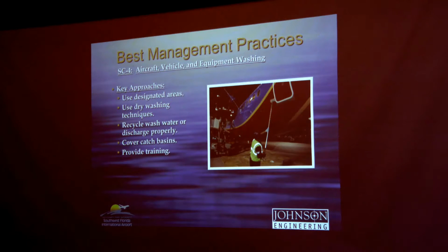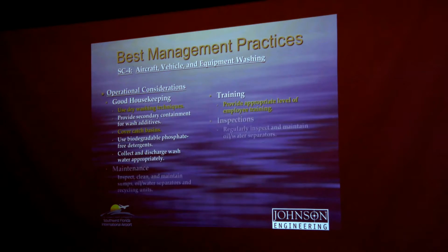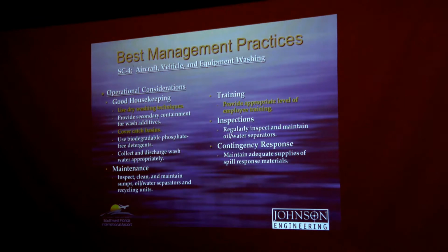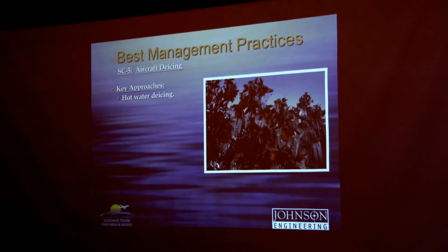SC4, aircraft, vehicle, and equipment washing. Key approaches here include using the designated areas, use dry wash techniques, recycle the wash water appropriately, covering catch basins, and providing employee training. Additional operational considerations include providing secondary containment for wash additives, using biodegradable phosphate-free detergents, collecting and discharging wash water appropriately, inspecting, cleaning, and maintaining your sumps and oil water separators, and maintaining adequate supplies of spill response materials.